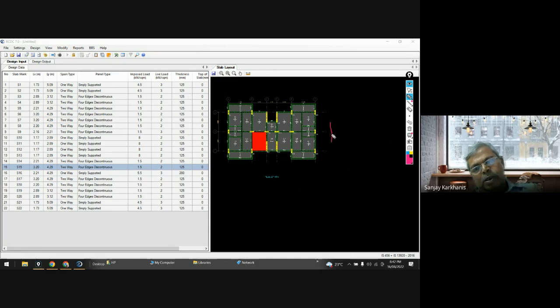See, if this is your span, you don't have a bending moment something like this. The bending moment goes on increasing as you go towards the span, and it goes on reducing as you go towards the support. It is not a constant like this.